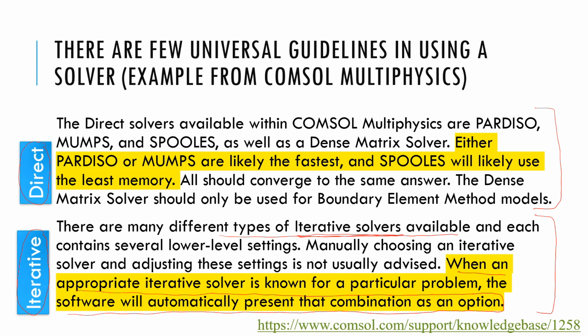And also they are saying manually choosing an iterative solver and adjusting all the settings inside the solvers, as I showed you, is not usually advised. So we basically leave it at default, and if that doesn't work, then we have to carefully look into it.